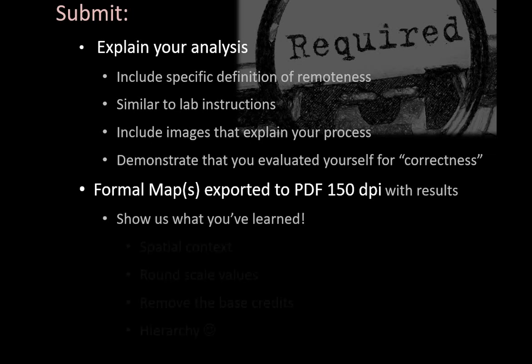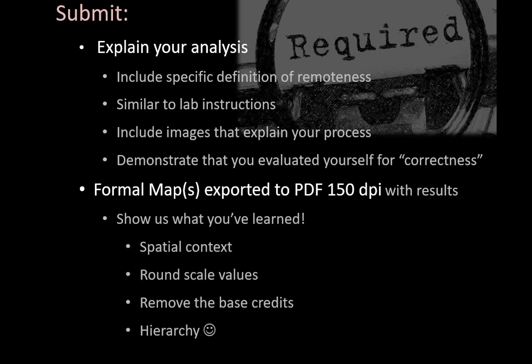Okay, formal map. Bring us your best cartography. Spatial context, so an appropriate base map, and that means choosing the correct symbology over a base map. I've given you guys some feedback about the aerial images, the satellite photos, and how detailed they are. Don't use a solid fill polygon on top of a base map like that. You're just covering up all that detail.